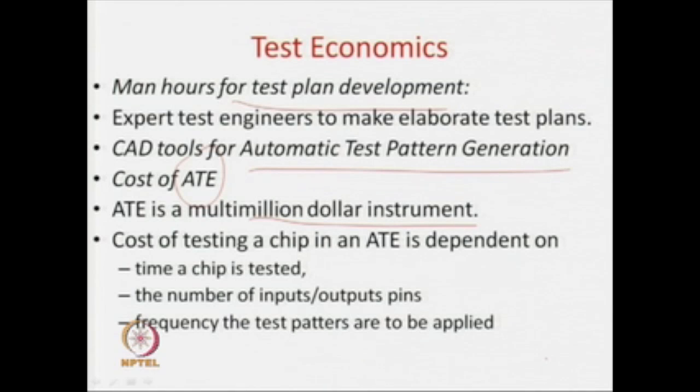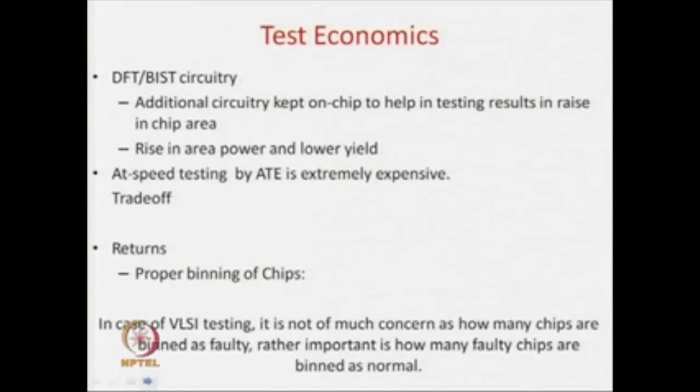Now, if you increase the test time, then you have to use more ATE and pay more money. But if you make a very intelligent test plan, so that with fewer patterns you can test your circuit, then you have a very good test plan. But again, then you have to pay, as very sophisticated or highly skilled manpower is required, which will again cost money. So, the whole testing process is basically about a trade-off of economics.